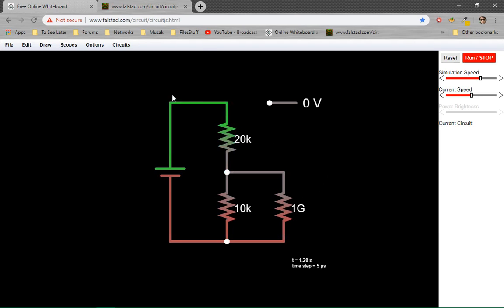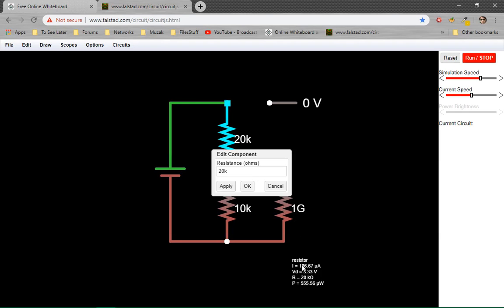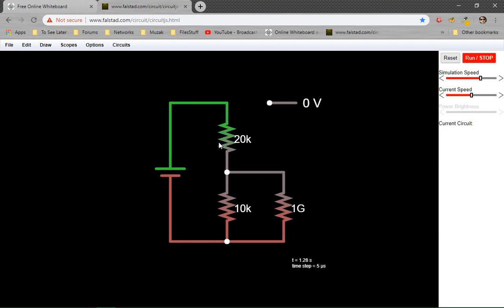When we design a circuit, we want to consume the least power possible. That means the smaller current, and smaller currents come from higher resistances. So the bigger the resistance we use for our circuits, the better. It means more energy efficiency. But there's this catch, which I've already mentioned, which is all real-world circuits will have noise, will pick up electric fields from the environment, the air.